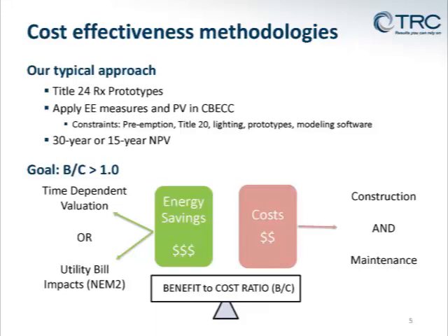The way we evaluate energy savings is through two ways. Time-dependent valuation. Who here knows what time-dependent valuation is? Okay, so about two thirds. It basically assigns a dollar value for fuel used at every hour of the year based on the demand of that fuel for that particular hour. So if there's electricity that's in really high demand at a particular time, it's got a very high value to it. The other way we look at it is just through utility bill impact. So for a normal person who is getting this utility bill, is it going to be cost effective for them, for the end user? So we try to look at it through those two separate ways to evaluate benefits, and then the cost is always going to be about the same.